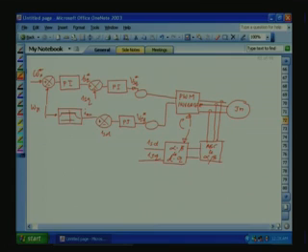We know that ISD will be equal to IMR in the steady state. If any transient flux weakening is there, this ISD by 1 plus S Tr, correct? This is the correct IMR. So, we will give it here. So, feedback and IMR will be the same.